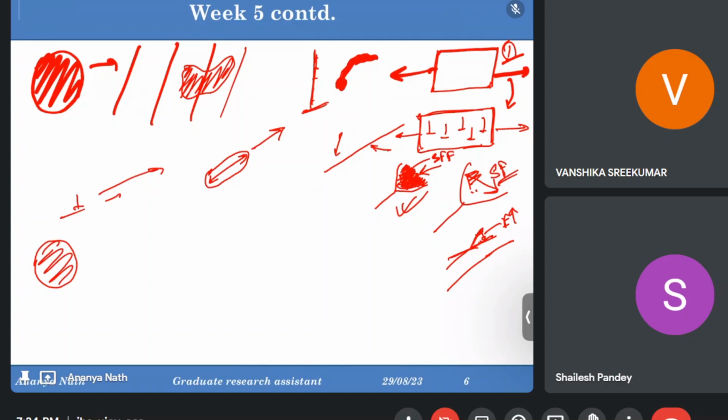For a single dislocation, there is no condition to move inside the material. Only if you stress, the dislocation will move. But for dislocation pile up, it needs another condition and some more properties, or some different situation to move forward. So that particular favorable situation is this cross slipping of the screw dislocations.